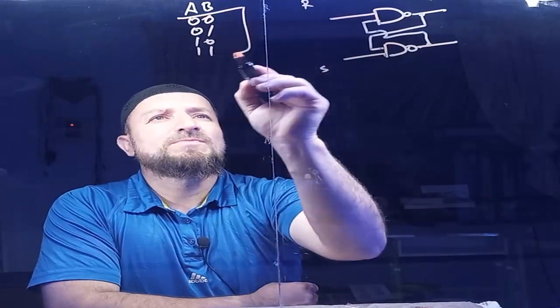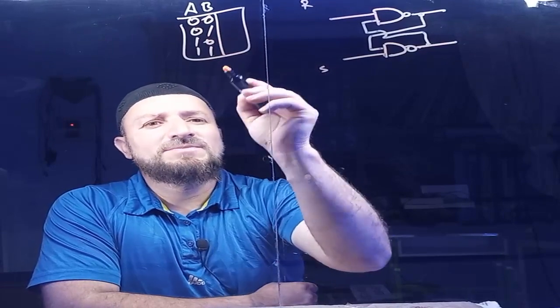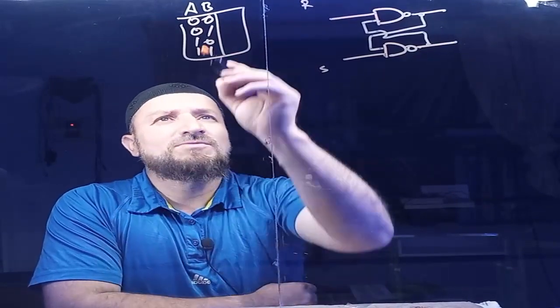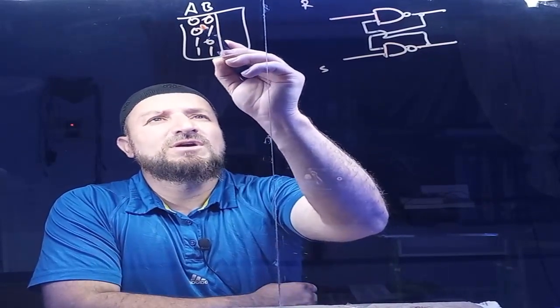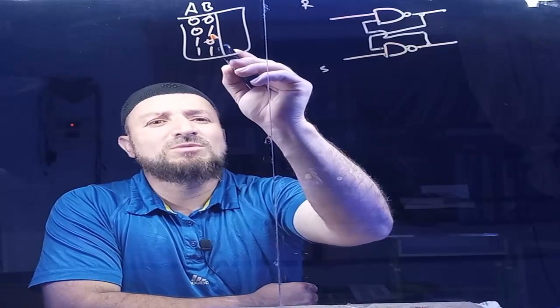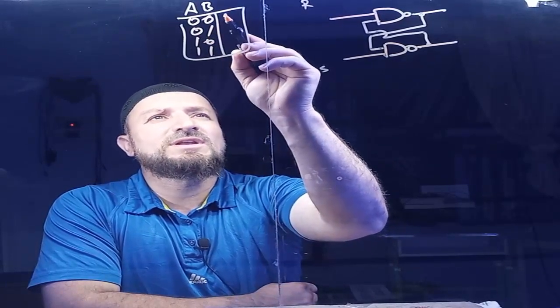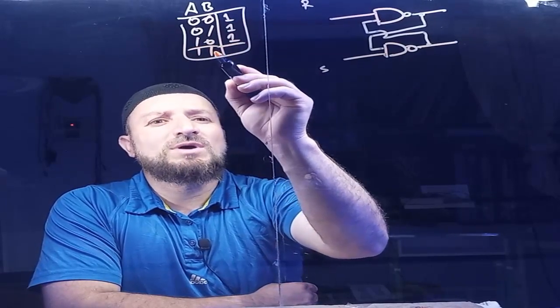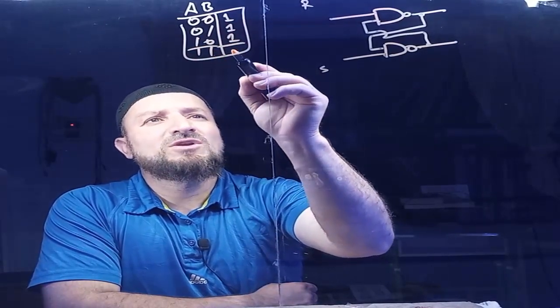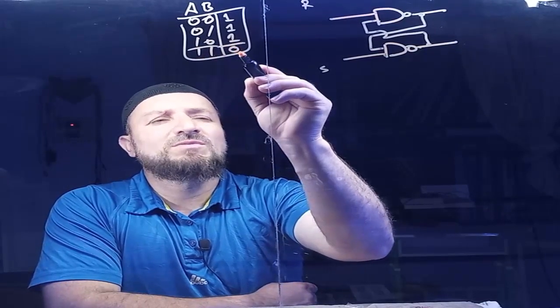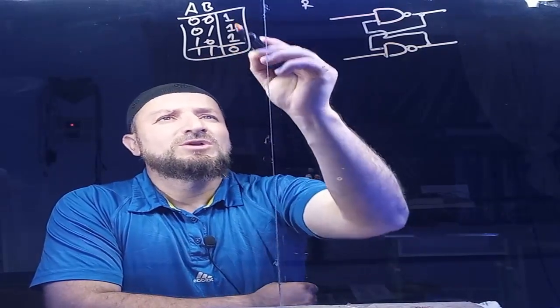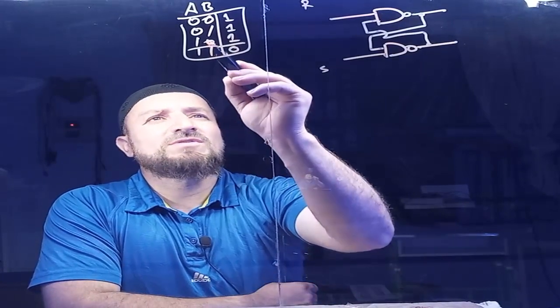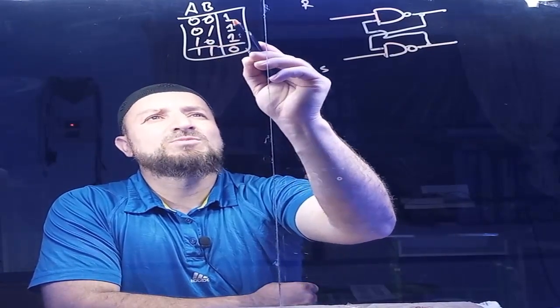The AND of the zeros, where there is a zero, is going to be 0, but the NAND of it will be 1. Only when it is 1 1, the AND of it will be 1, so the NAND will be 0. So the rule we said was: if one of the inputs is 0, the output is going to be 1.